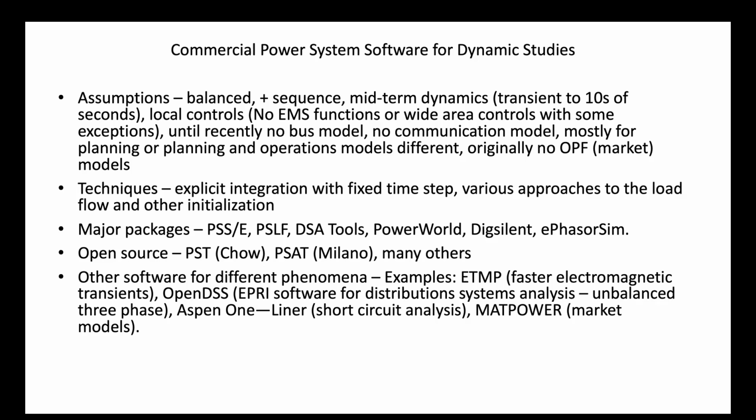Part of the reason for all these limitations is historic. They didn't really start doing these studies until about the 1970s. I believe EPRI was the first one with their extended ETMSP, which is the Extended Transient Midterm Stability Program. The underlying technique hasn't really changed in any of these. It's an explicit integration with a fixed time step, so it's not using modern integration techniques.